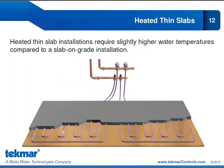The other type of radiant installation that works well with this type of geothermal system is a heated thin slab. Now this requires slightly higher water temperatures than the slab on grade, and that's because the slab is thinner than slab on grade floors. So it has slightly less heat dispersal characteristics, which translate into a slightly higher water temperature requirement.